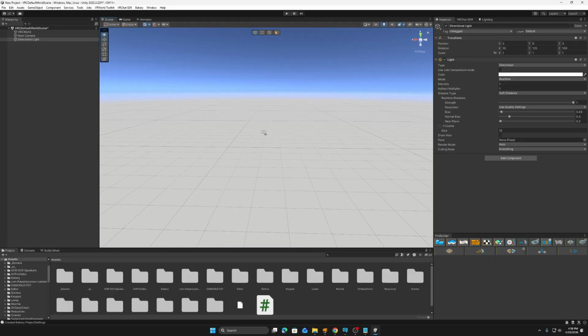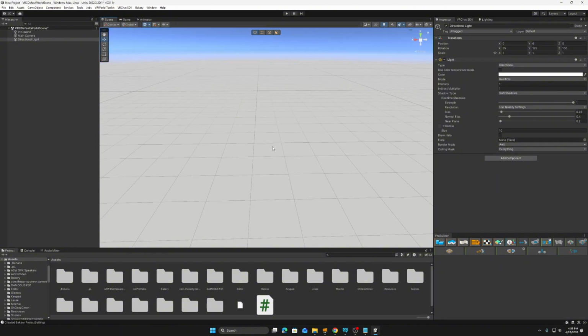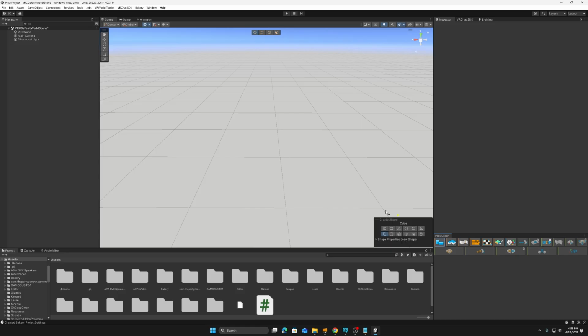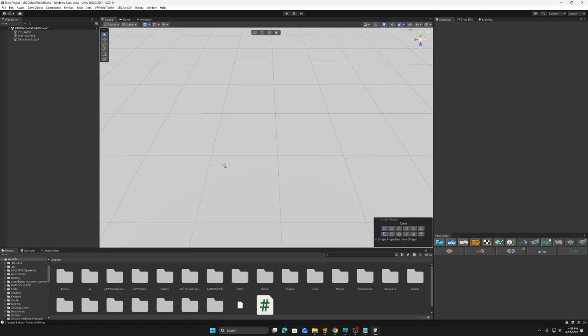But what we can do now is start building. So we'll build a base. I usually just build with a cube if I'm doing anything. We're just going to keep this very simple for the sake of the video. Hit Control and you'll grid lock with the actual grid. You just click and drag, and if you drag outside, you can let go and just free roam with it. You can move around, make it as big as you want, but if you hold Control, it'll still grid snap.